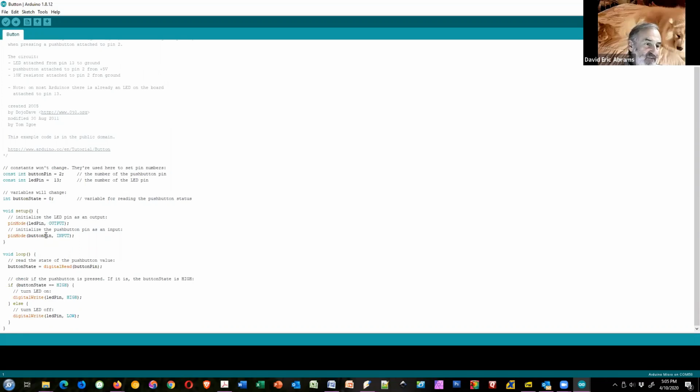Notice that it's using the button pin as input. This will not work unless you add a pull-up. So this should have INPUT_PULLUP as the correct code. But you can look at the code and see what it does. So I would play with some of the examples. Try writing something. So you have a push button. You also have some LEDs.